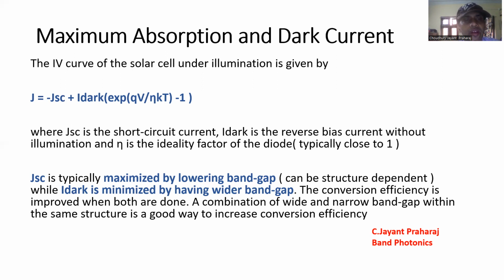defects. Now, there are dislocations in these materials. For example, there are threading dislocations, which are like missing lines of atoms, and there are vacancies in thermal equilibrium or even in non-equilibrium. And these introduce what are called deep states or mid-gap states. That means these are states deep inside the band gap of the semiconductors.